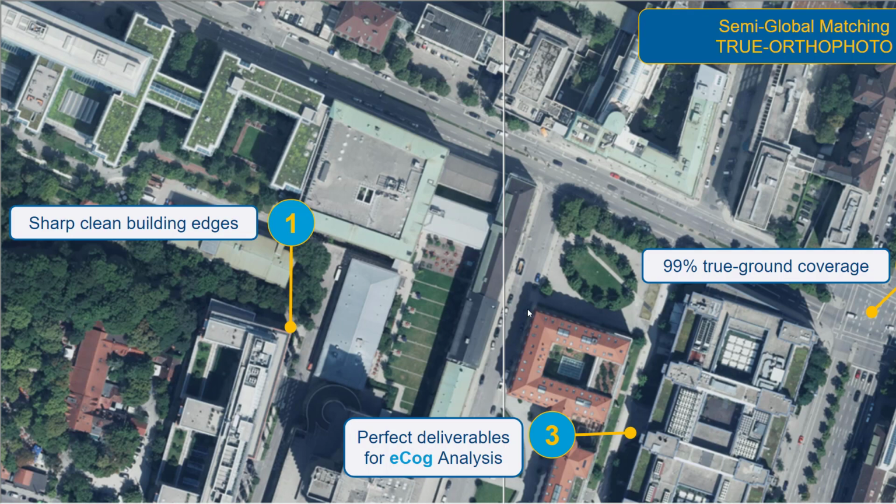You can still run the very fast and reliable digital terrain model approach for very large parts, which is very fast. Then you can still run the well-established digital surface model approach that we already have in Trimble Business Center from the previous versions. And now you additionally have this option to create orthophotos for urban mapping.